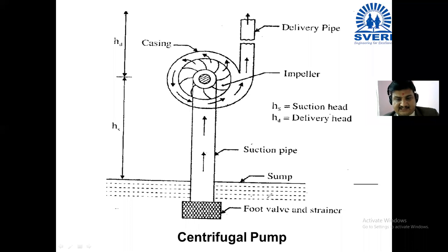Sometimes we use a terminology that the pump has left the water. In Marathi, we sometimes say that the water in the pump or pipe has run out, or there is no water in the pipe and water has to be filled into the pump. So when you are using this terminology, at that time you will have to understand there may be some problem in your foot valve. When there is some fault in your foot valve, your pump stops absorbing water, because the foot valve allows the water present inside the sump to come to the suction pipe. It does not allow the water present in the suction pipe to go outside again. So that's why the foot valve is very much important.